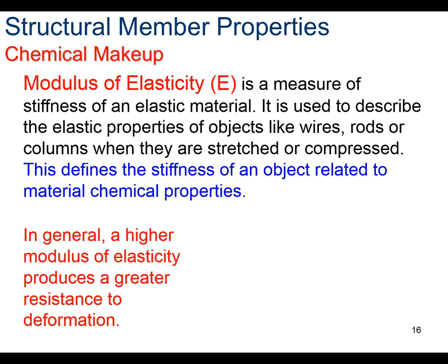In a later lesson, we will talk more about how the modulus of elasticity is calculated by comparing the amount of strain a material experiences per unit of stress. But for now, all you need to know is that the higher a material's modulus of elasticity, the less it will deform or deflect when a load is applied.